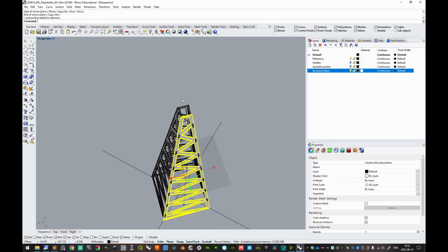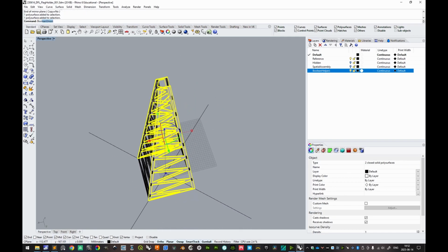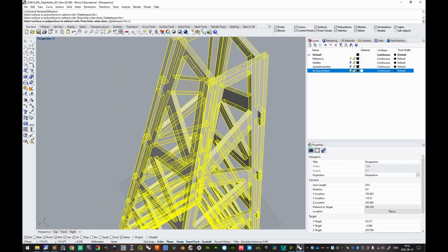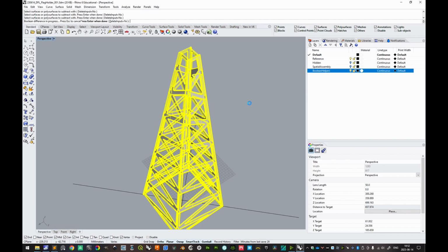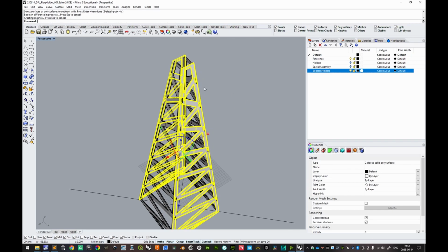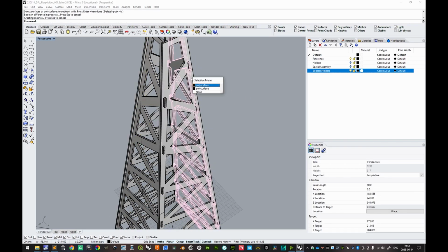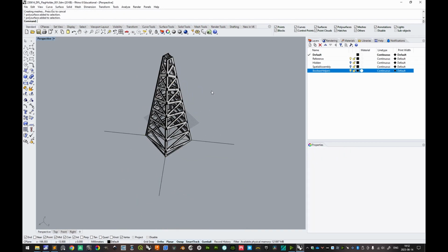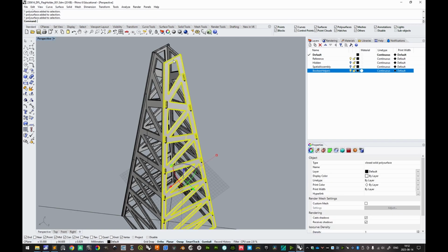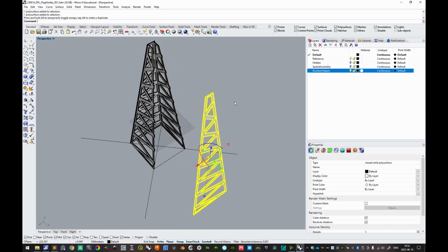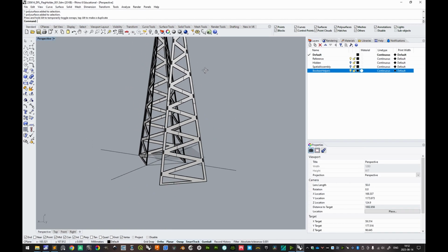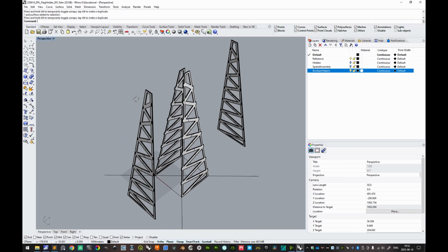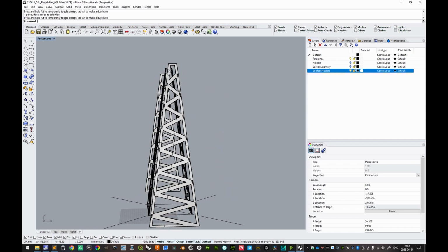So we'll take this one and do a Boolean difference. And then the selection should be the two there, and then we'll let that process. And we have, I think, the final result in terms of how they should be assembled. Yes, we have holes everywhere we want them, as well as here. Very good.